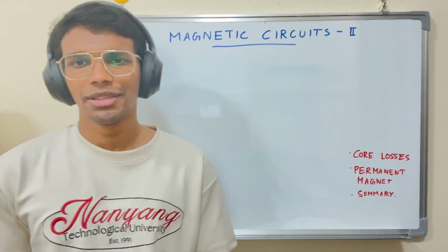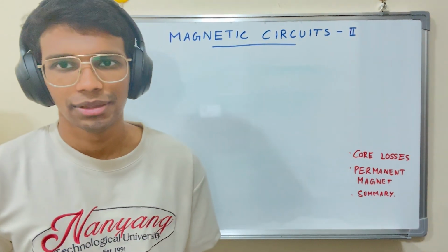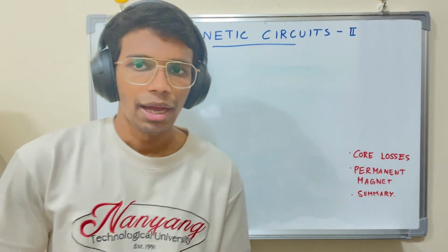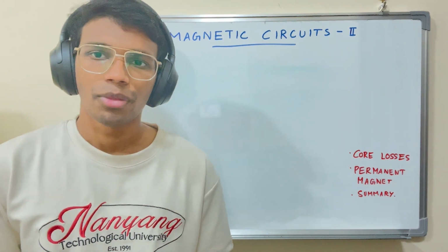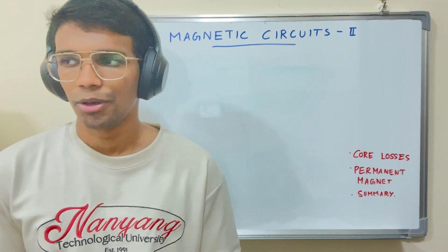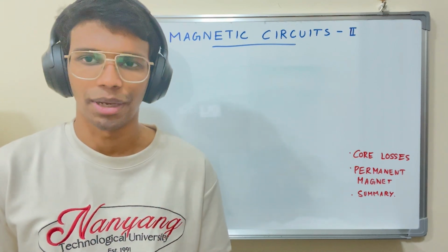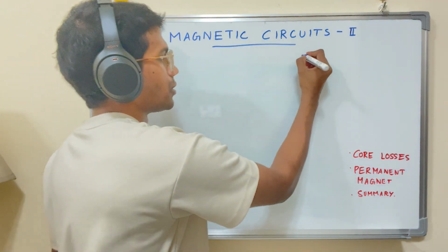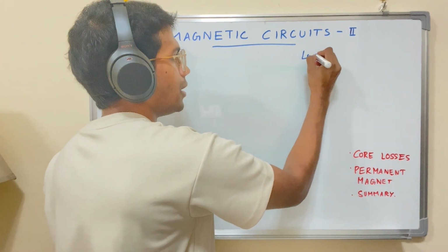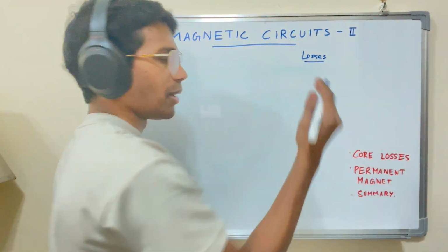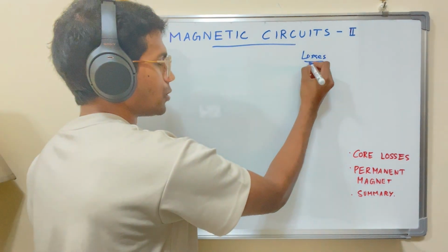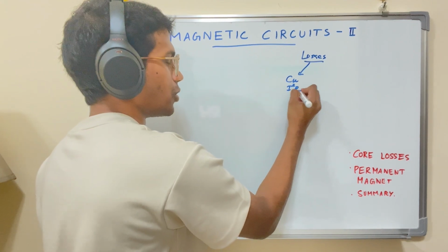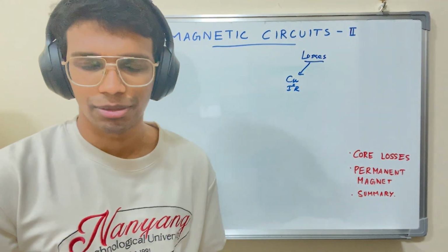Now here we'll be discussing the losses that occur during this BH curve, or this magnetization demagnetization process of a particular magnetic material. And why must we learn this, right? So first off, when we have an electric machine where you make use of magnetic circuits, like a transformer or a motor, you would have multitudes of losses, or well, just some categories of losses. So you inject some power into the machine, and some of it is obviously lost in the wire, in the copper windings, as I squared R losses. Of course, it's inevitable. If there's resistance, there are going to be losses by resistance.